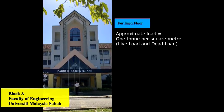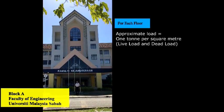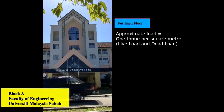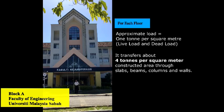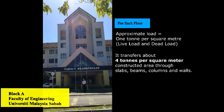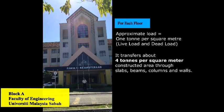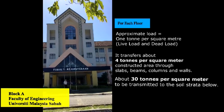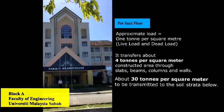Each floor thus has to carry an approximate load of 1 ton per square meter, live load and dead load. Thus it transfers about 4 tons per square meter of constructed area through slabs, beams and columns, and finally through the walls.